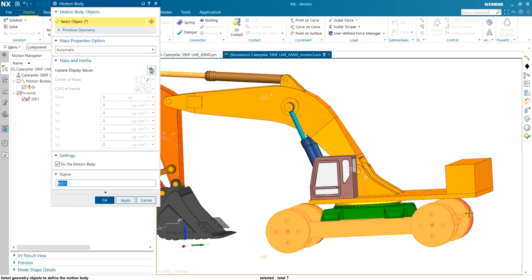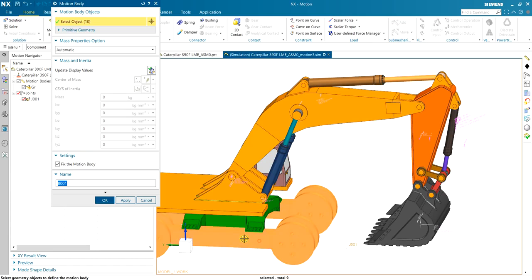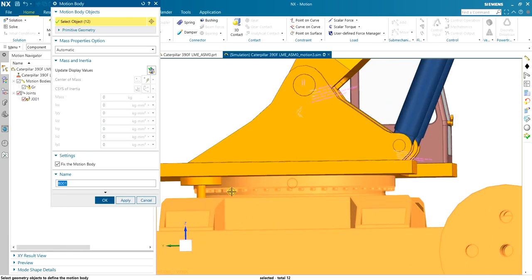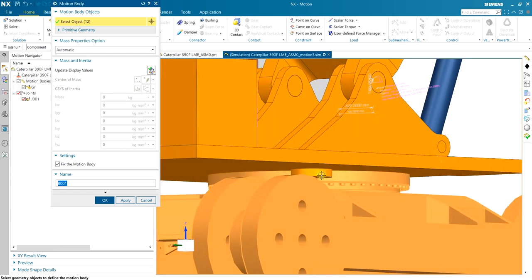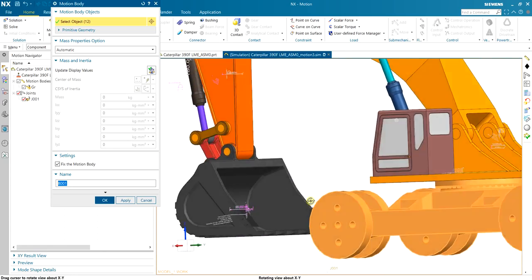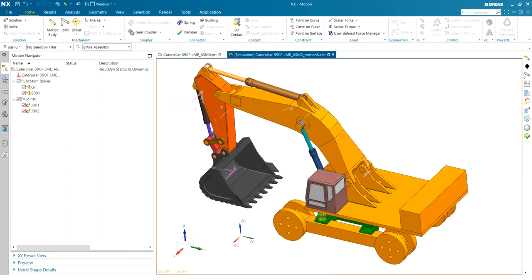So all the stuff down here, I don't want them to move. I'll add them. This is stuff, the motor and gears and other stuff there. They don't weigh that much, so I don't add them to the simulation. It makes the simulation faster.